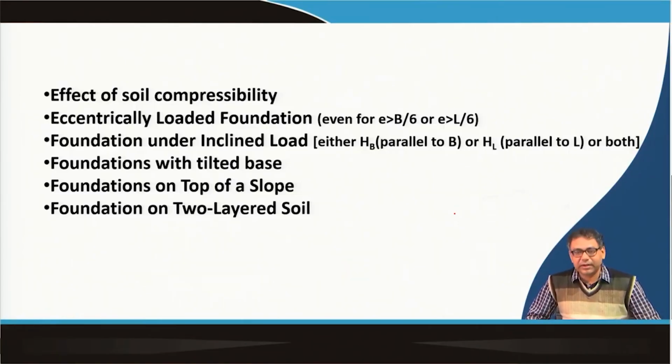Then in most cases we consider the foundation base to be perfectly horizontal, but if the foundation base is tilted, then how can we calculate the bearing capacity? Then if the foundation is on top of a slope, how can we calculate the bearing capacity? And very important, in our normal foundation design we take a weighted average value for layered soil. But if the foundation is resting on a two layer soil system, for example clay above a clay, or the top layer is sand and the bottom layer is clay, then how can we calculate the bearing capacity? Those things will be discussed.